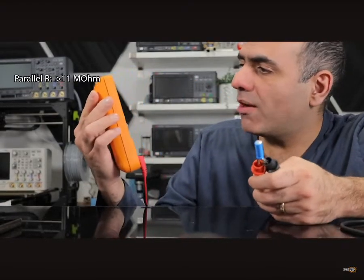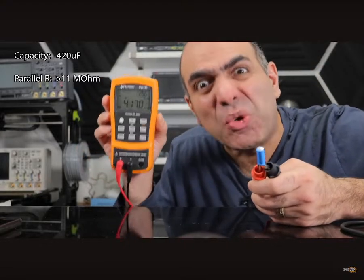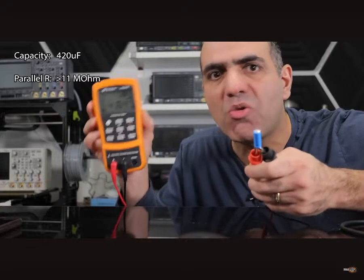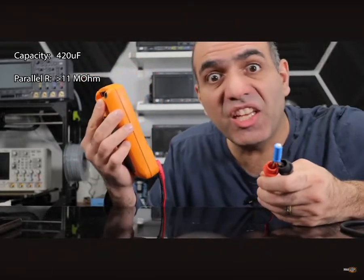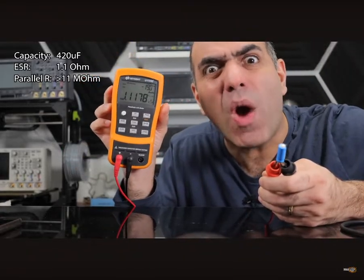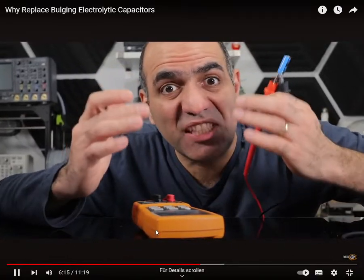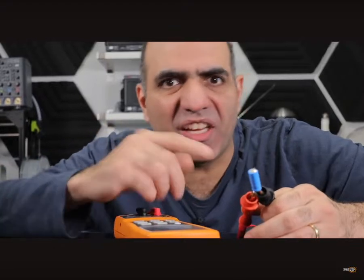The capacitance now is only around 420 microfarad. Dropped way down from the original 2200 microfarad. And the ESR now is 1.1 ohms, over 10 times what it was before. I mean, it takes a lot of talent to be able to half break a capacitor after how many minutes now? So it is still a 420 microfarad capacitor, but it is capacitating much less than before.